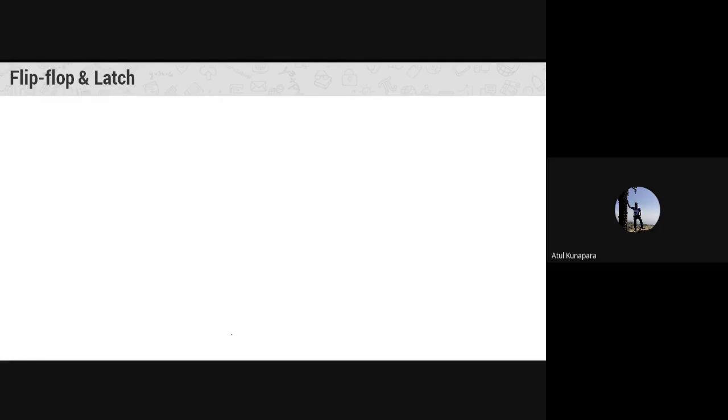So a large number of circuit components is required. Here we are going to start by discussing that smallest unit. Your sequential logic circuit will have a smallest memory unit which is able to store 1 bit of data. It can store either 0 or 1. Only 1 bit, not more. That is the smallest unit of memory, and that is where we start, with a latch.